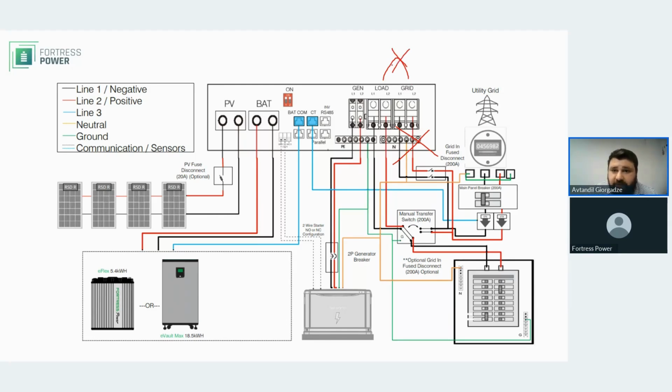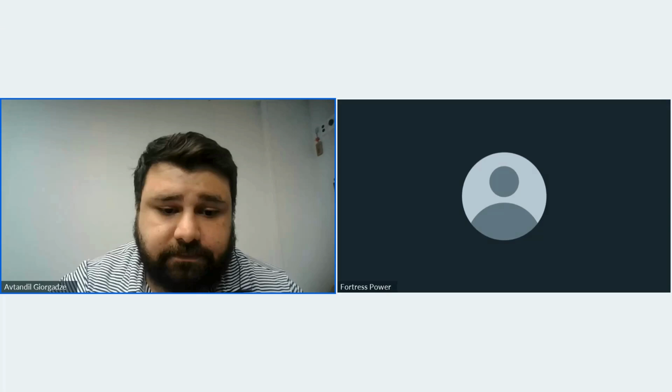So nothing can travel beyond that anti-islanding device. And again, we're keeping things safe here. You will also notice that we have DC coupled PV ports on our inverters. That's because we essentially have those string inverters built in.